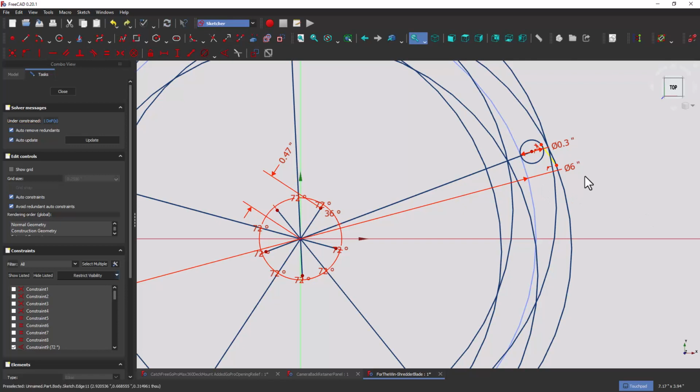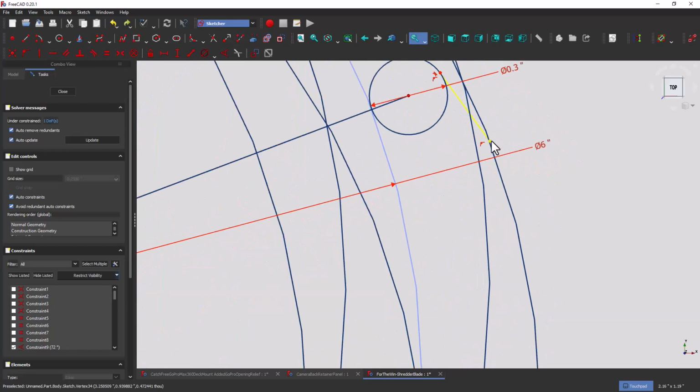Not sure why. Let's take a look at why that is. What's going on here? Is this really on the circle? It's attached. Oh, well, it already has tangent on there. I think it might have understood that. It automatically put it in there, but that's an extra one. There we go. It only needs to be tangent. What I just deleted was it had not only the tangent constraint, but it had a redundant, hey, that vertex is on the circle. So you can't be tangent without being on the circle. I just deleted that. It normally automatically deletes that for you, okay?